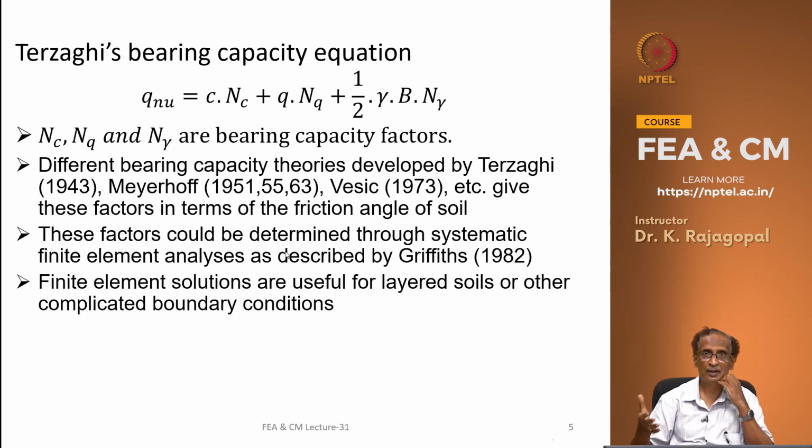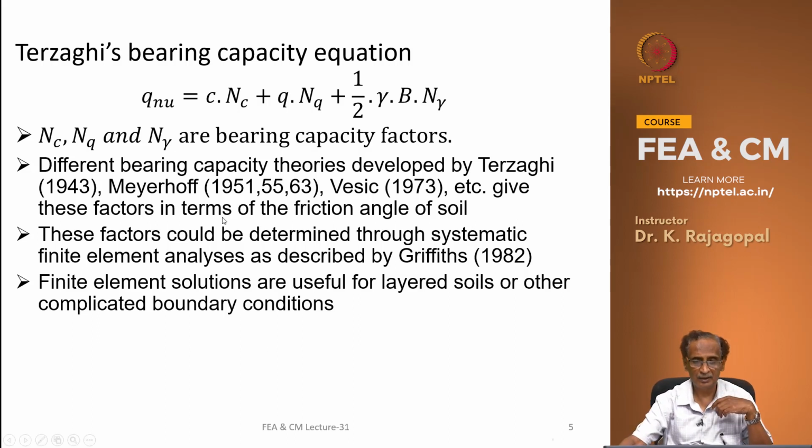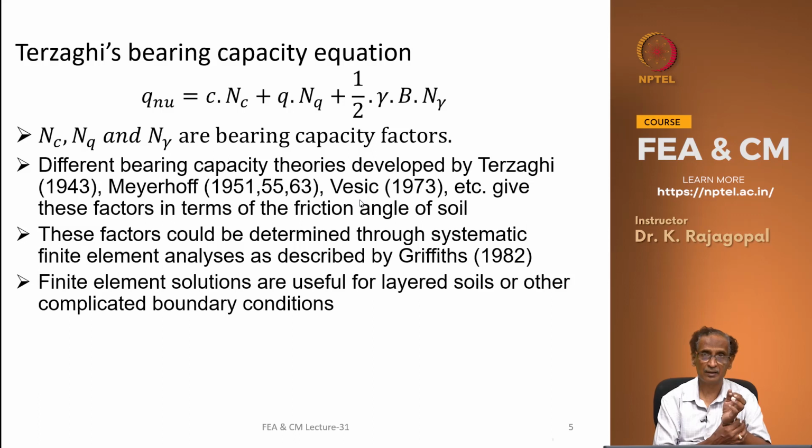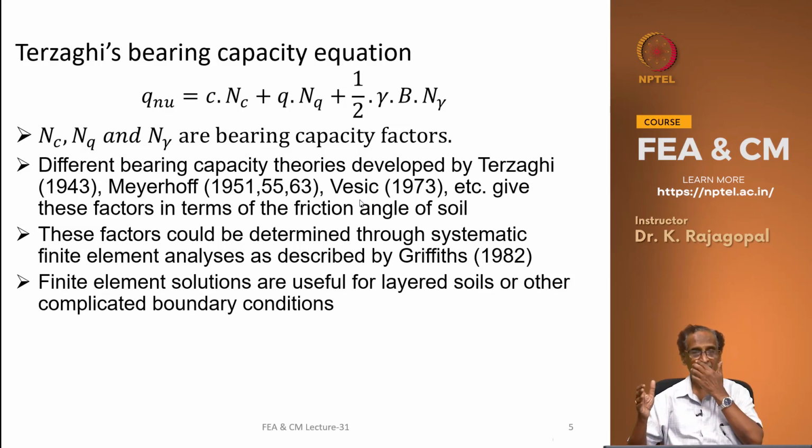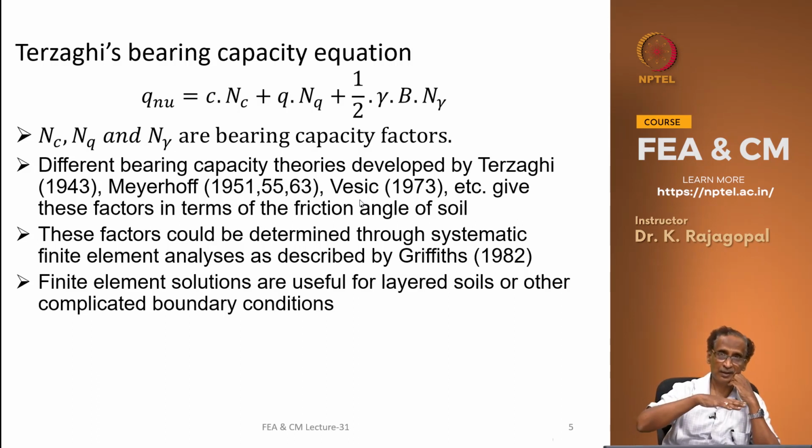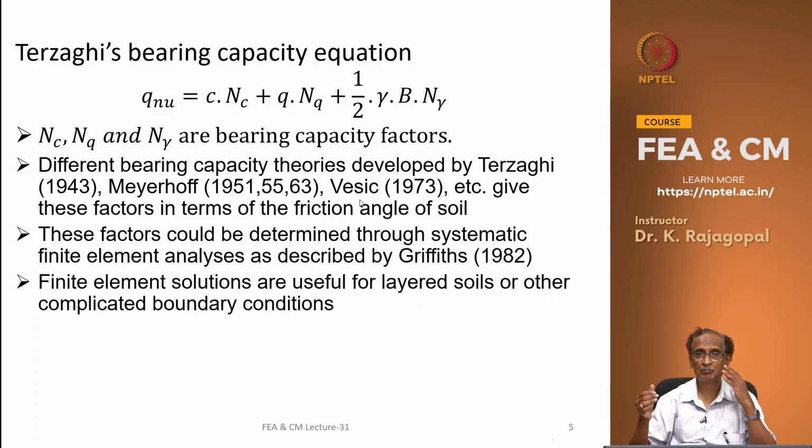You cannot use any of the existing theories, because all these theories by Terzaghi, Meyerhof, Vesic and so on, only assumed homogeneous soil conditions, and they assumed that the boundary is far away. But in some cases your hard strata may be at a shallow depth compared to your foundation width. In that case your actual bearing capacity may be much more than what these theories predict.